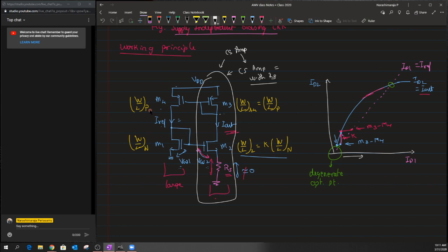Okay, so there is basically a shift that is happening, and this in turn we know that the gain of the CS amplifier with a source degeneration resistor Rs will have some sort of degenerative effect at the bottom. Roughly, I could say that it is something like this, followed by some quantity that basically divides this gain. This quantity depends on the value of Rs, or basically the drop across Rs, due to which the gain through this structure becomes smaller. So whenever the gain through the second structure becomes smaller, then the current gain from this M1 towards M2 will also get smaller and smaller.